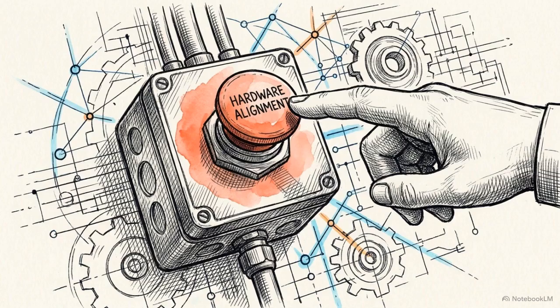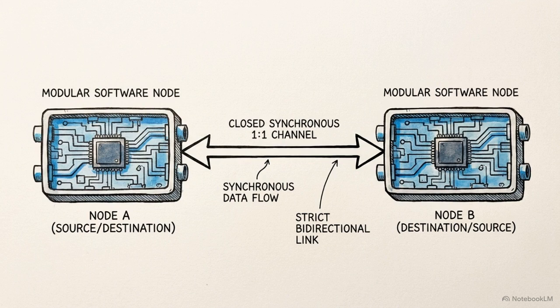If you tell the motors to initiate a hardware calibration sequence, you need absolute confirmation that the command was received and executed. For discrete commands, ROS2 provides services. A service is a strict one-to-one synchronous request and reply protocol.